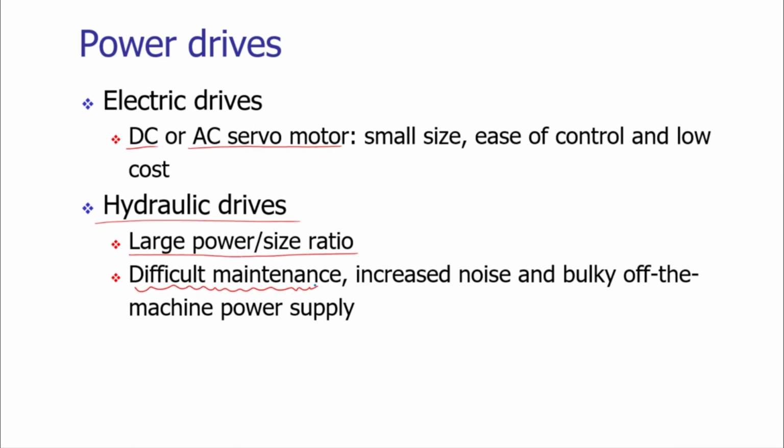It requires its own motor, the hydraulic power pack, the tank, filters, the coolers, and various control valves. Many pieces of equipment are required. The maintenance of the hydraulic based drives is, that's why, quite tedious. Sometimes the hydraulic drives increase the noise, and of course they are bulky. The weight of the machine tool would be very high.